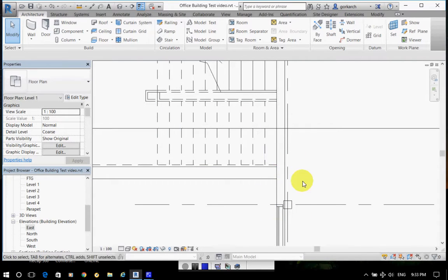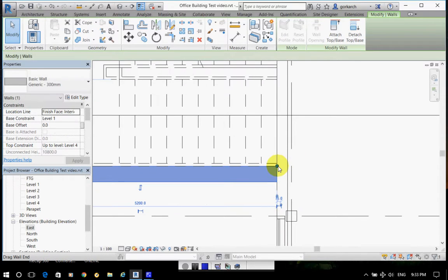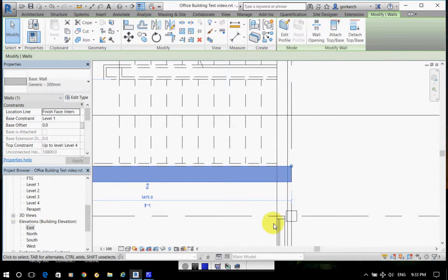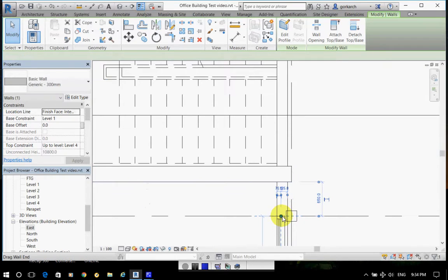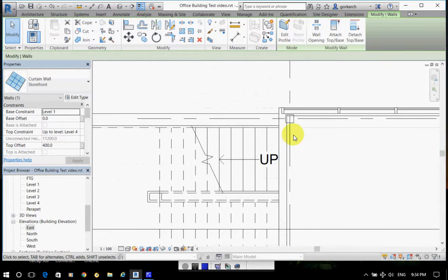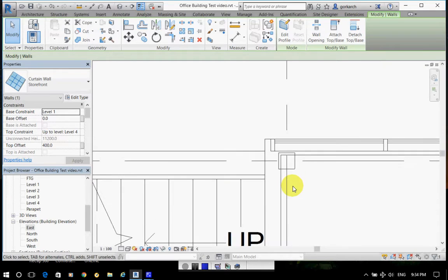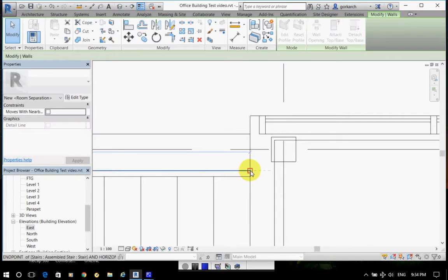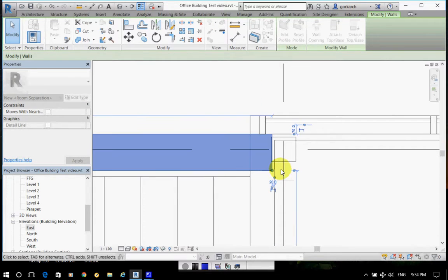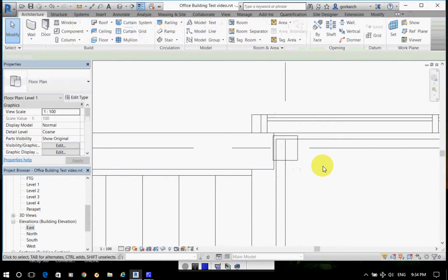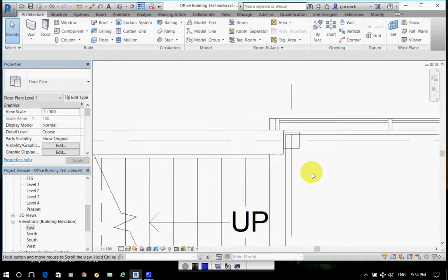To prevent the elements from getting into the building, obviously you have to make sure that there's no gap here, so stretch the wall all the way to the grid line, select your curtain wall, attach it to the face of the enclosing wall. Here we'll do something else. Stretch it so it touches the face of the column. You don't have to be precise for now, we'll handle that detail later, but at least we have some kind of reassurance that there's no gap.